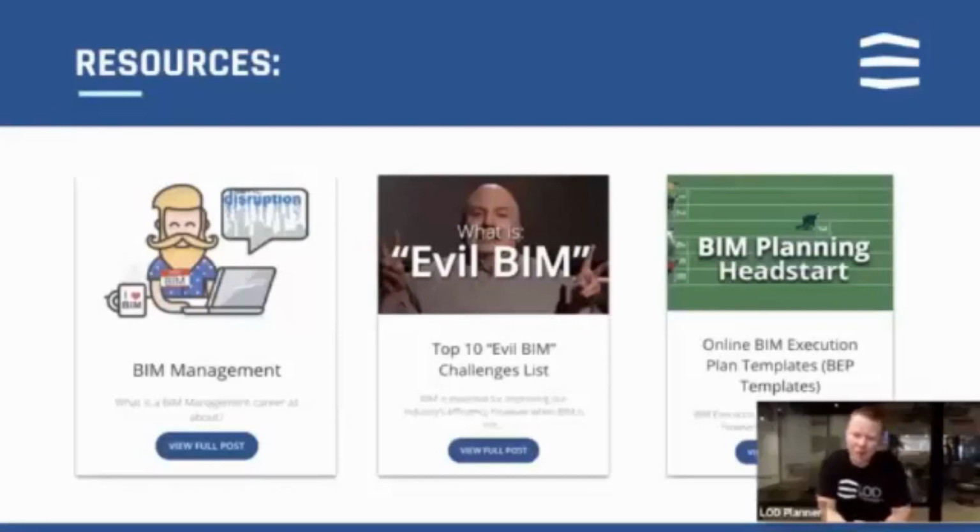Definitely start with hand drawings. Definitely start with thoughts and sketches at the very early stage. You know, sitting in the coffee shop with a napkin sketch. But get to BIM as soon as possible, way before you think about creating any drawings as an output. The concept of when does BIM come: does 2D come first and then 3D, or is it 3D and then 2D? It always has to be 3D first if you want to get the efficiencies from BIM. Because once you've created a 3D model, I just slice through that 3D model and I've got my drawings. So I would be crazy to do it the other way around.